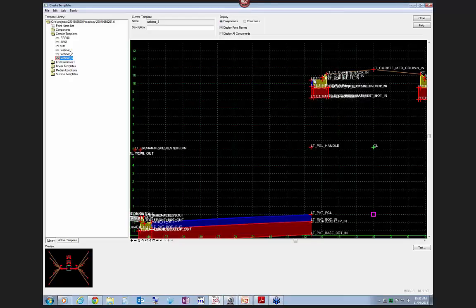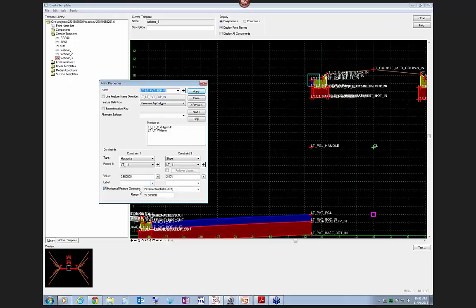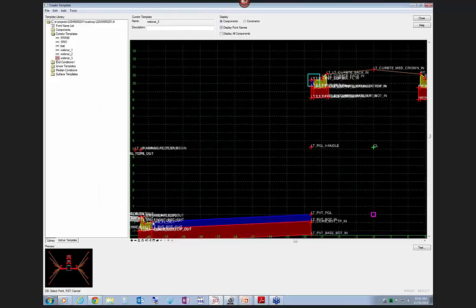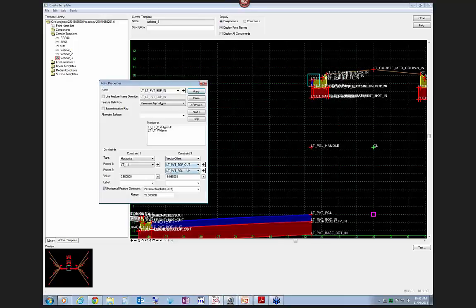For example, this slope right now is supposed to move in at a 2% according to wherever that left turn bay lane would be. If you want this to follow the same super elevation as this pavement, then what you would do is put in a different type of constraint. The constraint would be called a vector offset. And you would basically pick between this point and this point as the vector that you want this slope of this pavement to follow.